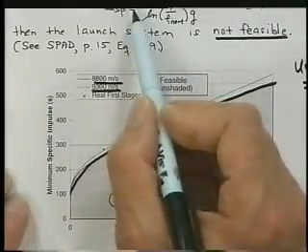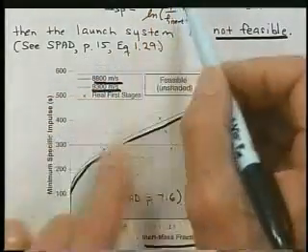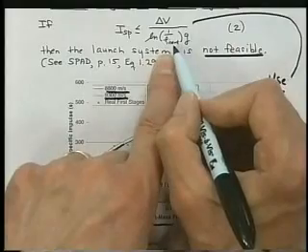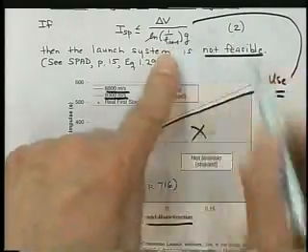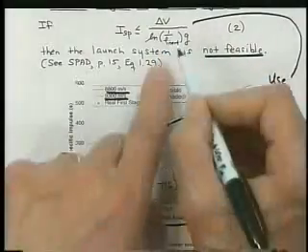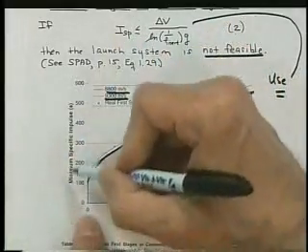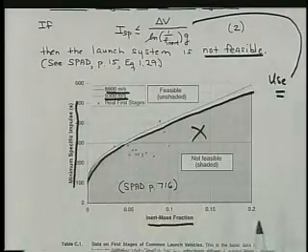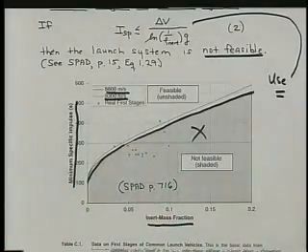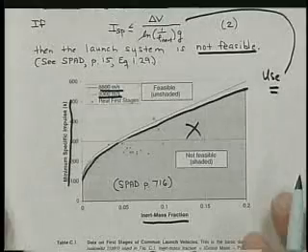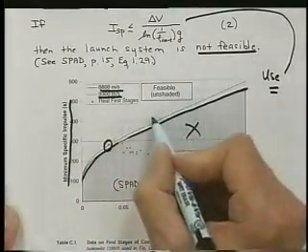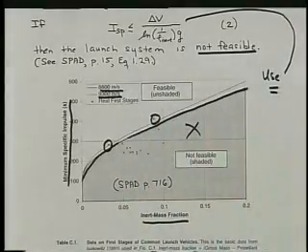So we set this equal, and we put in delta V, say, of 8,800 meters per second. We put in the standard G, which is a number that's defined, and then we put in values of F inert, which is the value on this axis, and out comes ISP on this axis. Okay. So it's ISP as a function of F inert. And then anything in the gray area is not feasible for one stage. Notice that there are actually, interestingly, two values here that are above the curve.